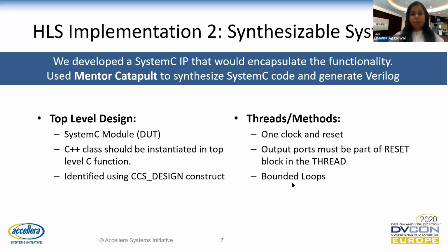Every thread and method should be sensitive to at least one clock and reset signal. Any output port being driven in the thread must be part of the reset block of the thread. Any loops used inside the threads or methods need to be bounded.